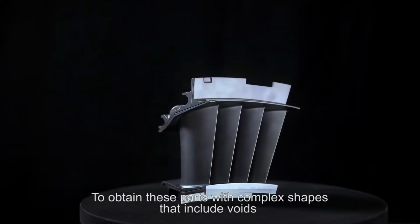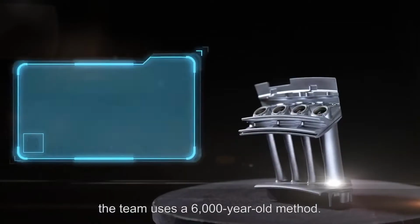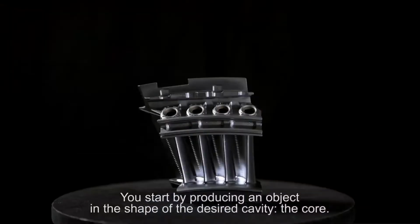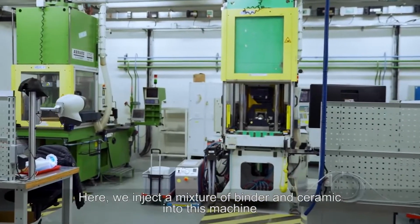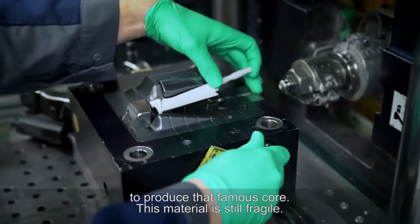To obtain these parts with complex shapes that include voids, the team uses a 6,000-year-old method, lost wax casting. You start by producing an object in the shape of the desired cavity, the core. Here we inject a mixture of binder and ceramic into this machine to produce that famous core.